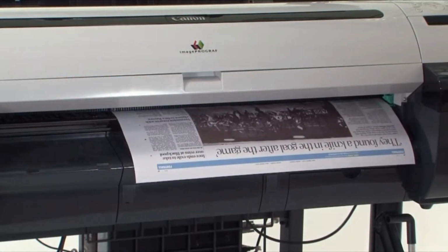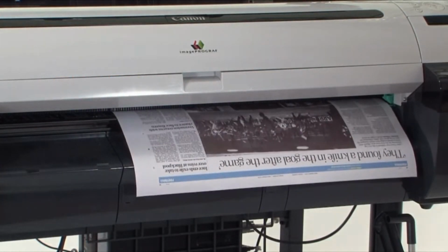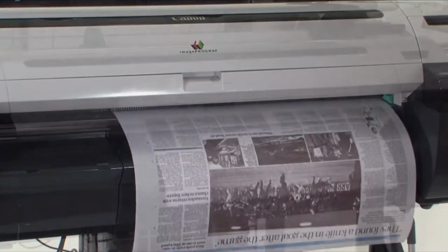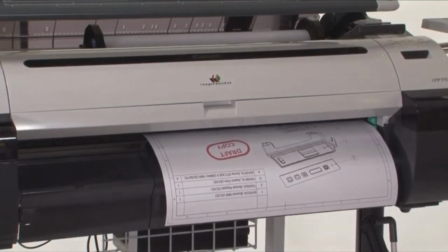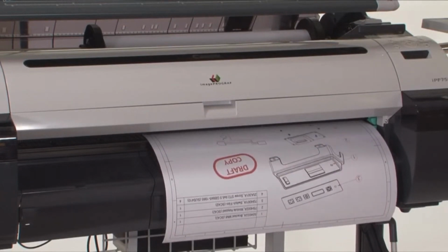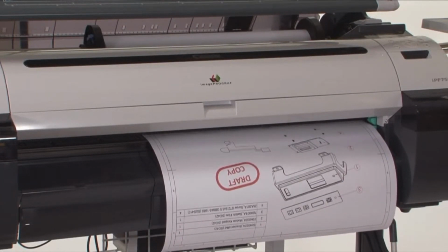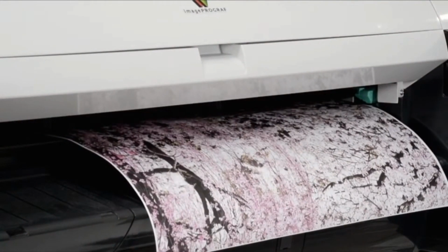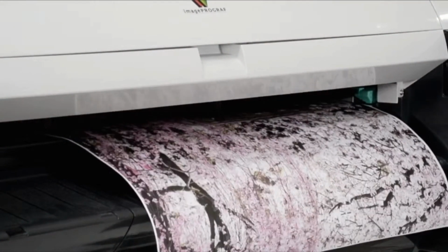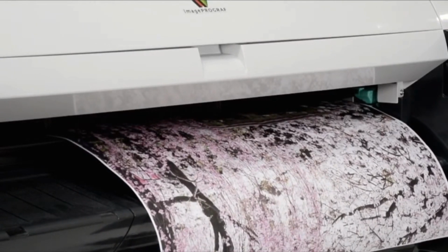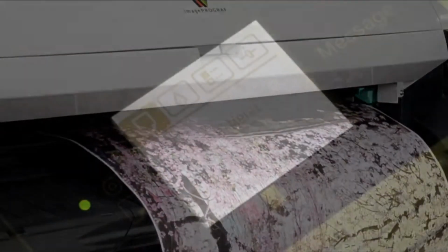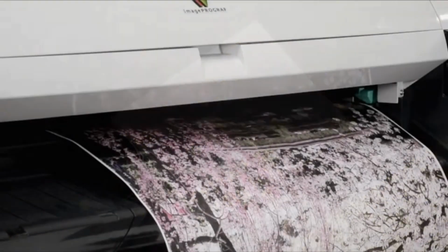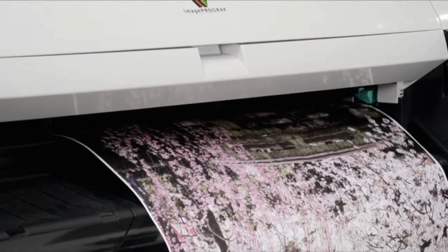Being able to print using SmartWorks Pro's internal drivers can be very useful where Windows print color is unsatisfactory and because of its ability to calibrate printer and paper for ultimate color accuracy. This can also considerably speed the printing process, particularly at high resolutions, because the printer can start before the scan finishes. To begin, ensure that the printer is installed with the correct media type, particularly when printing full-color photographic images, when it's recommended to use high-quality photographic paper.